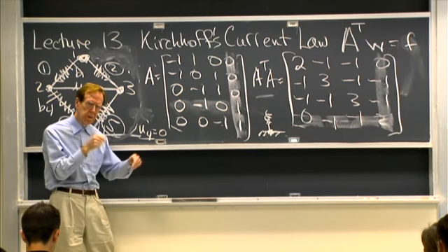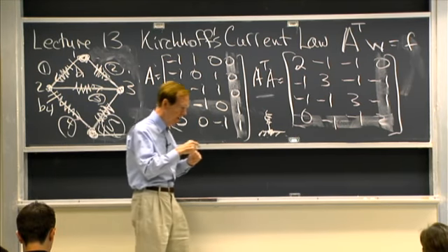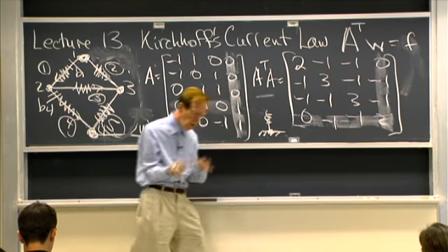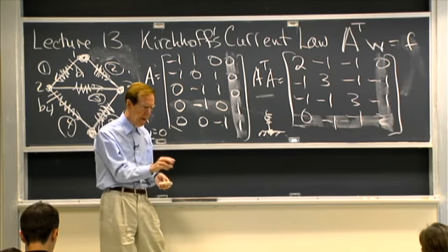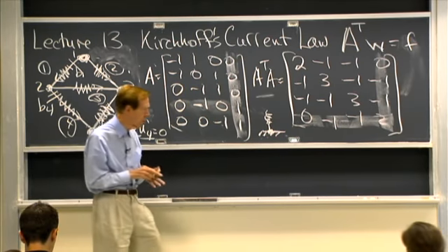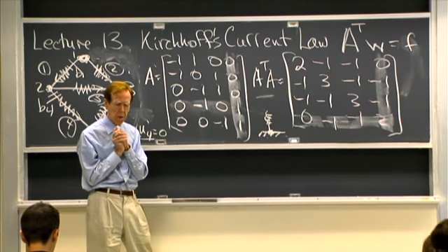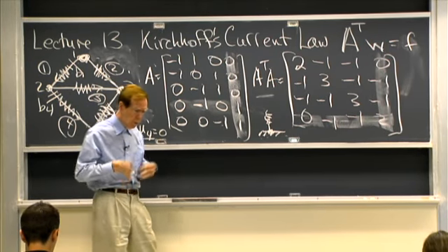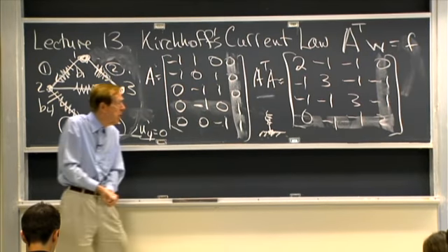So, in other words, let me say that again. The force balance will hold, and it will tell me, after I've solved the rest of the problem, what the support has to supply, how much force the support is actually supplying. It's a reaction force, it would be called. So a reaction force is whatever the support has to do to fix that displacement.